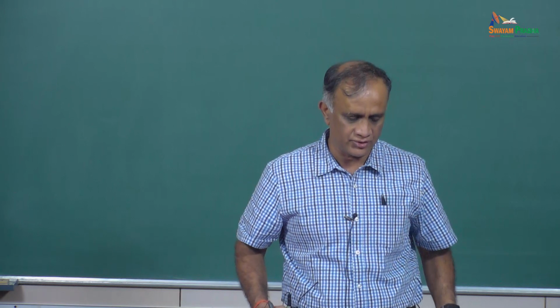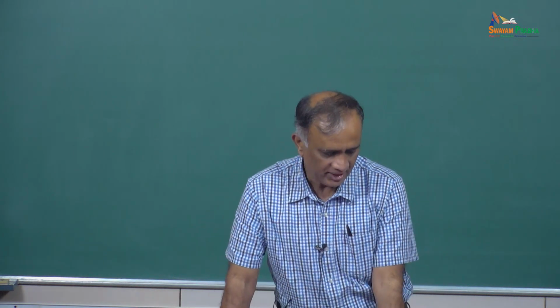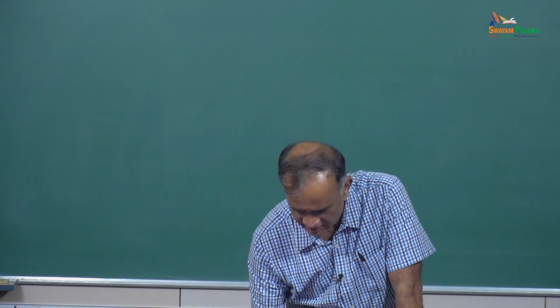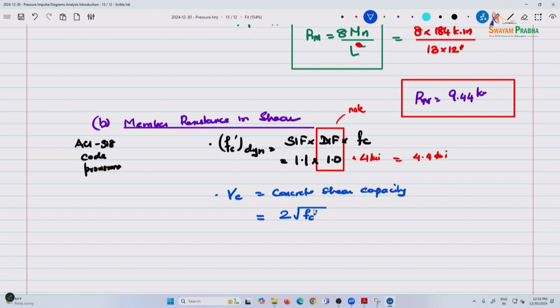So, there are provisions to include some of those, but even the simplest form has changed, but we will use, ignoring the effects of reinforcement ratio. The reinforcements provide additional shear strength. In slabs, of course, you do not have shear stirrups or the dowel action. So, ignoring those actions, and for our course purposes this is fine.